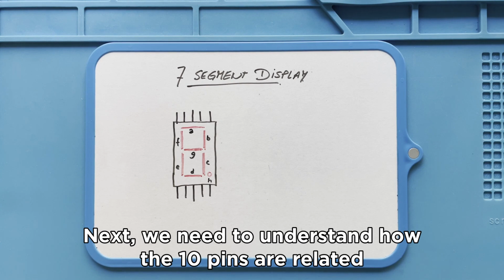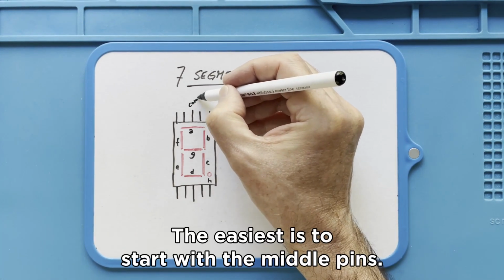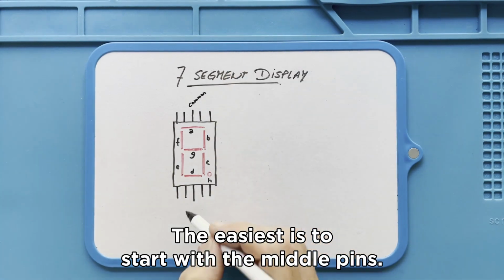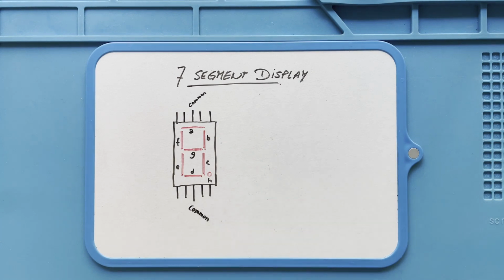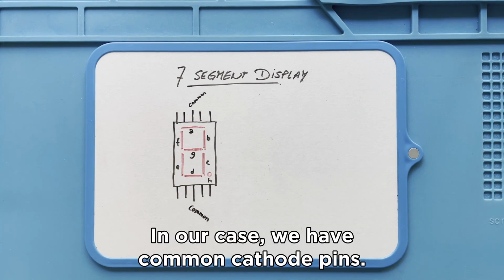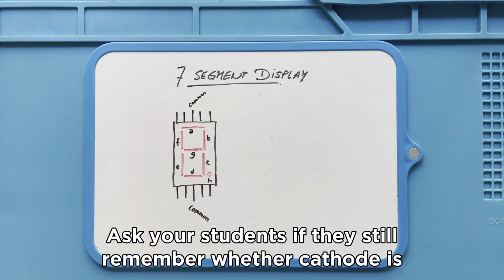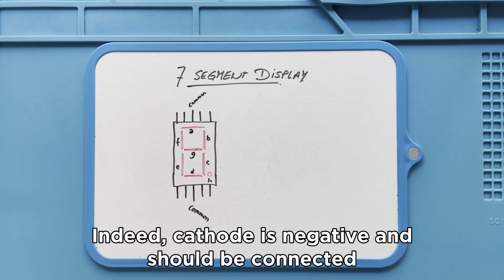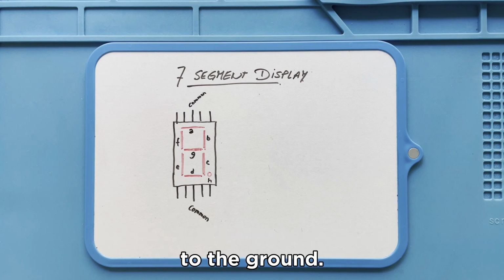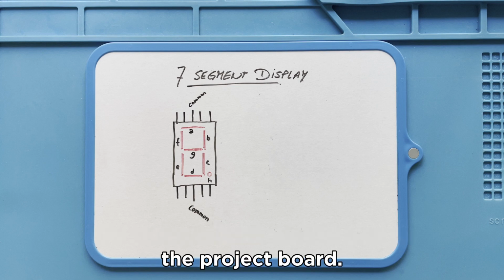Next, we need to understand how the 10 pins are related to the LEDs. The easiest is to start with the middle pins. These are your common cathode or anode pin. In our case, we have common cathode pins. Ask your students if they still remember whether cathode is negative or positive. Indeed, cathode is negative and should be connected to the ground. We connect both middle pins to the ground rail of the project board.